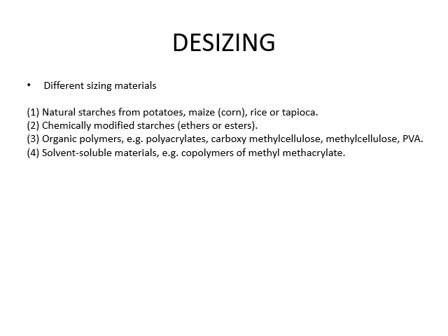Vegetable starches like cornstarch or rice starch are mixed with water and cooked. They form a strong, smooth, water-insoluble film. In order to desize these materials, they must be degraded to water-soluble components by using alpha amylase enzymes. This is followed by rinsing the fabric multiple times with water to remove residues.